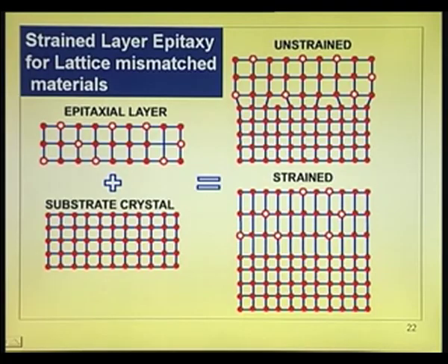I will go through this particular detail the next time, but this is the substrate of one lattice constant, and this is the substrate of another lattice constant, which is more. If you arrange, you can get this type of structure where the intermediate layer is defective, you can see the bonds are broken. That is what you get. If you grow lattice mismatched devices, tremendous stress is there, pulling each other, and defects will be generated.